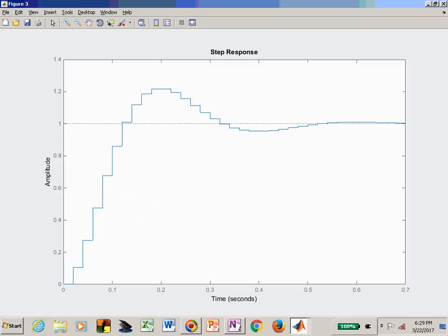So I would not put in a 1, I would put in a minus 1, and then it tells you that you are not specifying the sample period. If you put in a 1, then if you do anything else with that transfer function, it's going to be assuming that the sample period was 1. And that may not be what you want MATLAB to be thinking or using.